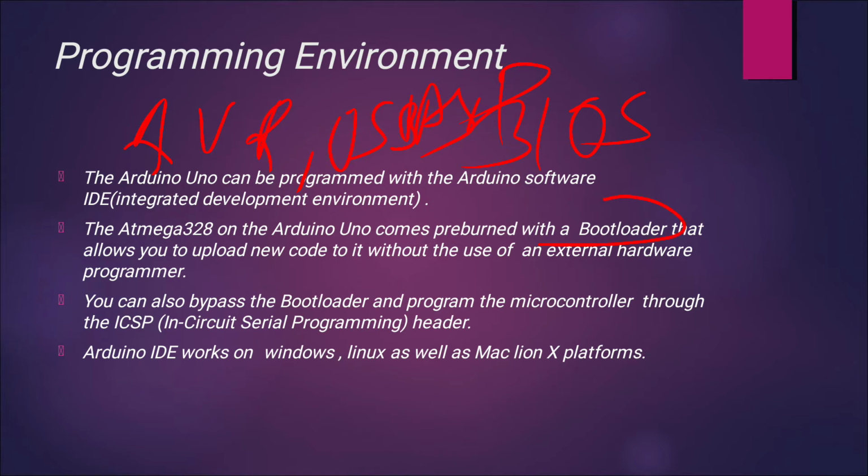The bootloader allows you to upload new code to it without the use of an external hardware programmer. You can also bypass the bootloader and program the microcontroller through the ICSP, in-circuit serial programming header.